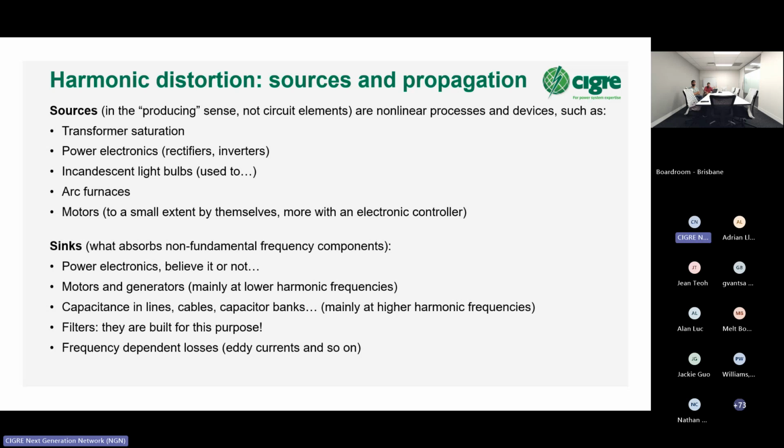Yes, they create lots of harmonics. And motors, especially if they have an electronic controller, so almost everything gives harmonics. Sinks: what absorbs these components that are not at 50 Hertz? Where do they tend to go? In the power electronics, believe it or not, because we said it's a source, but it does also